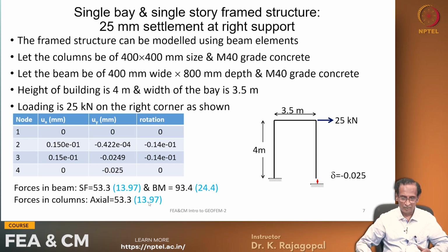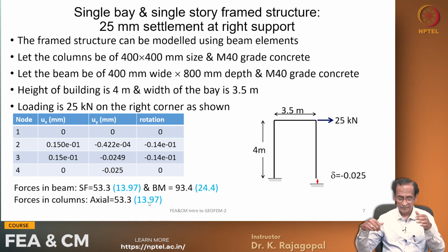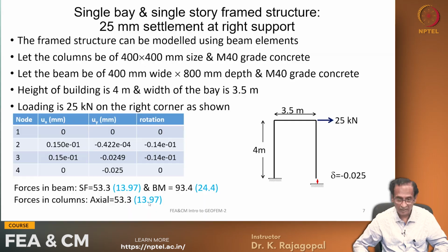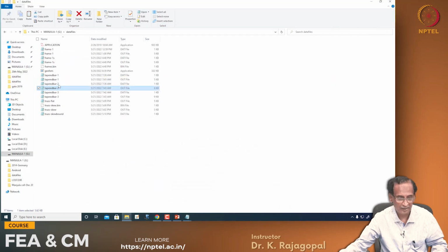Also, one important lesson that we learn is, if your structure is going to undergo any relative deformations, we have to take care of the additional forces that are generated, additional shear force and additional bending moment, so that we can provide sufficient steel reinforcement to prevent cracking. I think that may be the last one, and let me show you these data files.